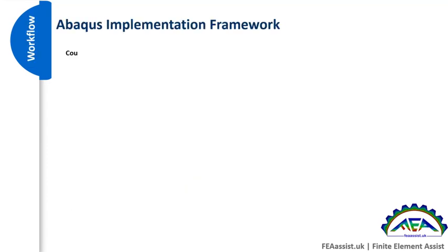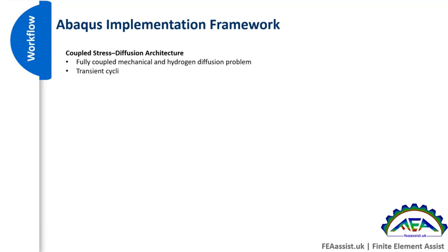Workflow, Abaqus implementation. It is a coupled stress diffusion architecture. So, a fully coupled mechanical and hydrogen diffusion problem. And we will have transient cyclic loading with time-dependent diffusion and crack tip boundary layer formulation.